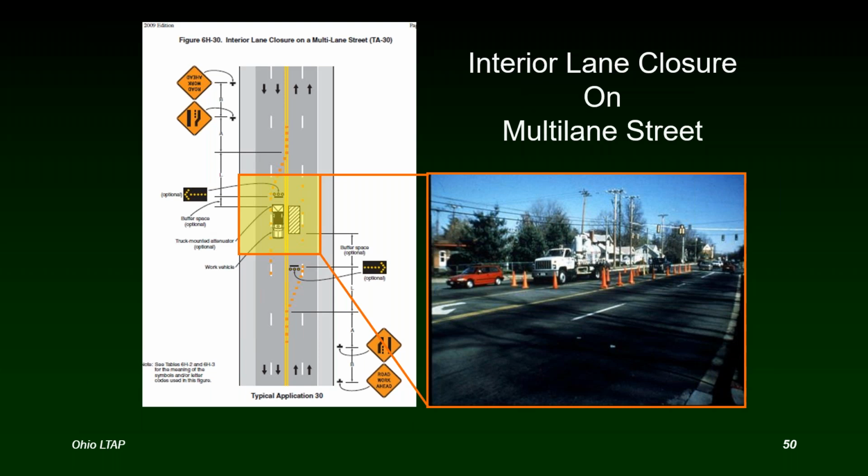And of course, in the last 5 years, we've kind of waged war on 4-lane roadways, because we know that a high volume 4-lane arterial doesn't work very well in urban areas because there's always a car stopping in the interior lanes trying to turn left, and they block traffic, and they cause a lot of crashes. And so we've done a lot of road diets on these 4-lane roads, and always consider widening them for another lane, which is the center 2-way left turn lane in the middle, which solves a lot of problems as well. However, there are still a lot of 4-lane roadways out there, and so we have a lot of different typical applications for these 4-lane roads.